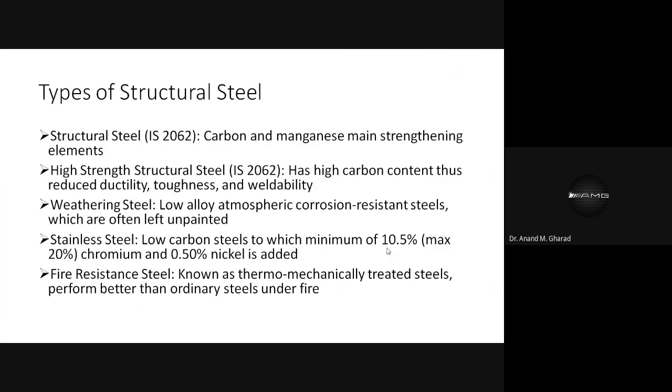And we saw there are different types of structural steel present. So all the structural steels conform to IS 2062:2006. Now there is one more version which is 2011. There is a slight change as far as the terminologies for different grades of steels are concerned. So we will also see to it.